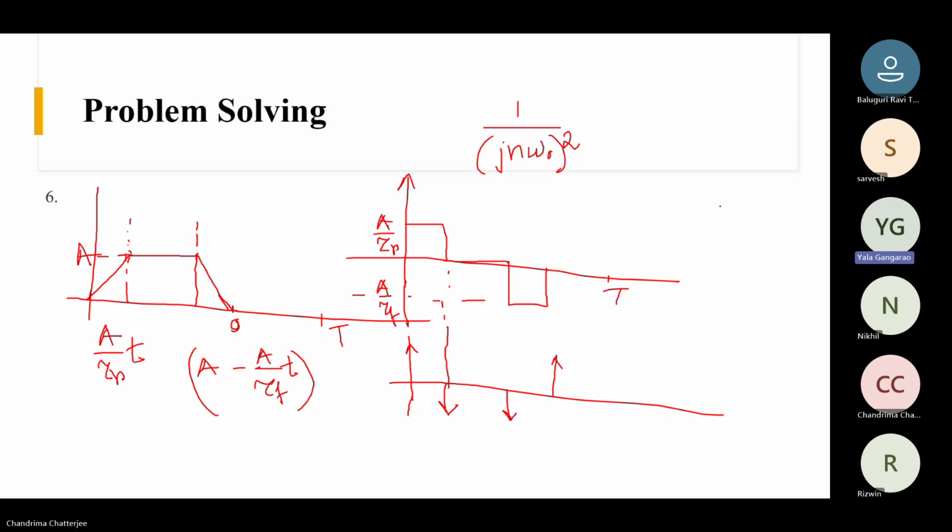Right now, say I am using ABS. I put ABS in the vehicle, and at the same time the display cables and everything are in that same bike. They should not interact with each other. Whenever ABS applies the brake, any magnetic field or surge current generated should not affect the other equipment. In a general EMC test they give the level and the range of what affects the other equipment.